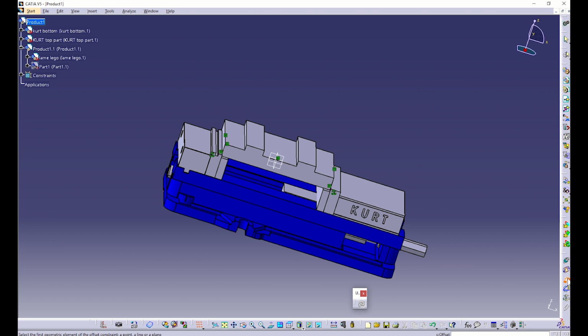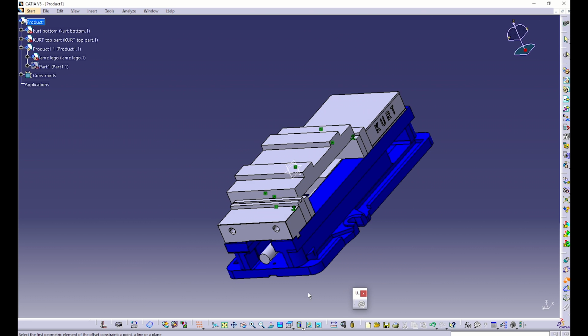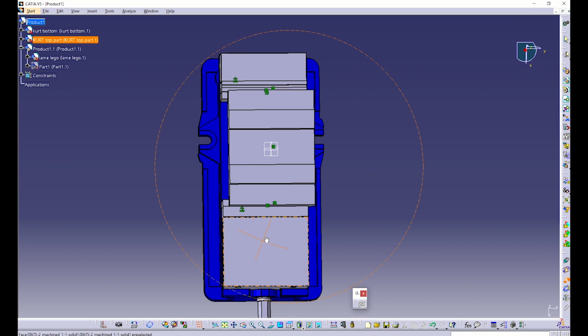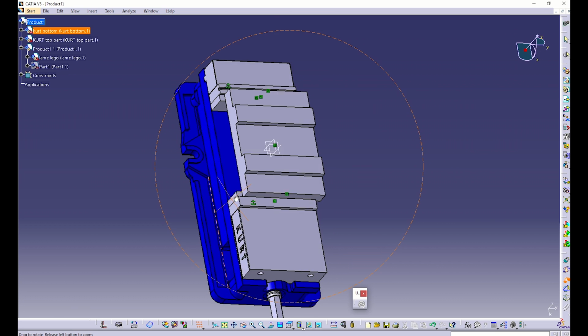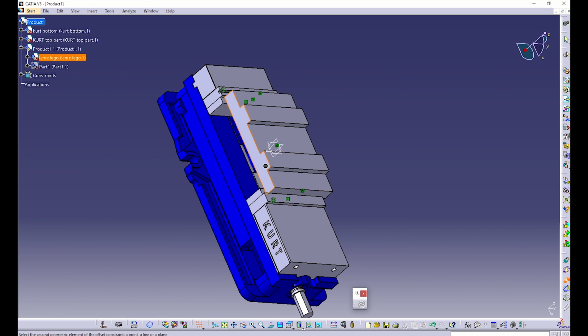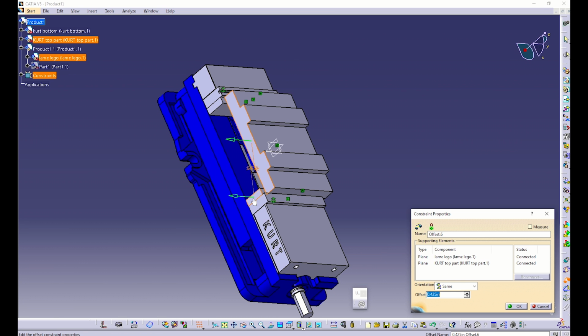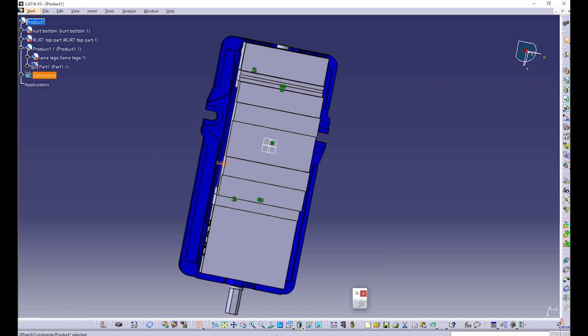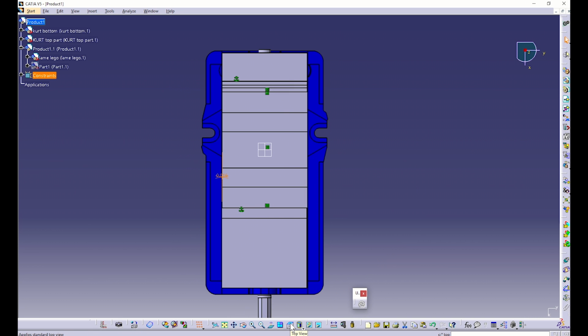Yeah, so I went ahead and clicked on this top view here. So we need to line it up. We got the face to this face. We're going to offset it like we calculated, 0.016, and update it. You can see it move over, but it doesn't look like it's quite centered.